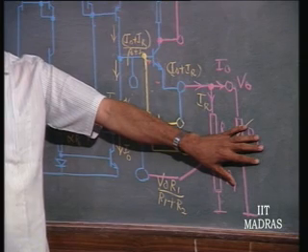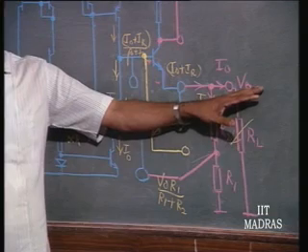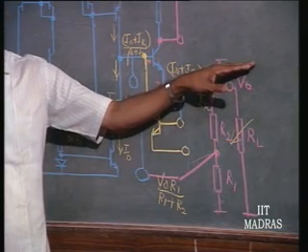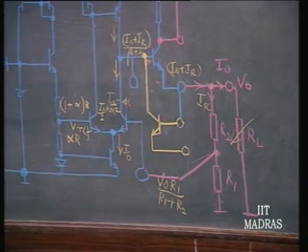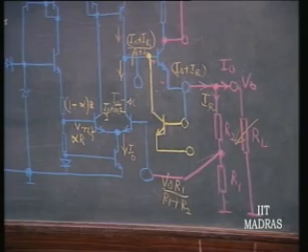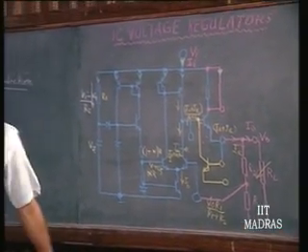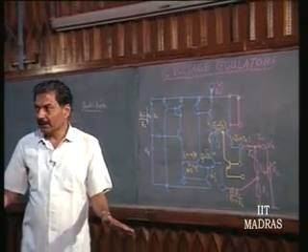So, one way to do it: this is nothing but a voltage source now. That is why, irrespective of the load, output voltage is remaining constant. At this point of time, I would like to convert it into a current source. That is the protection. The moment current is trying to exceed a certain value, I do not want this circuit to behave as a voltage regulator.